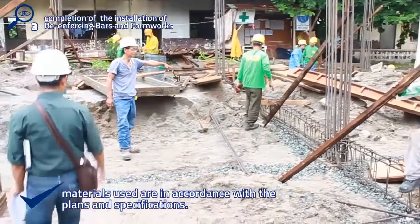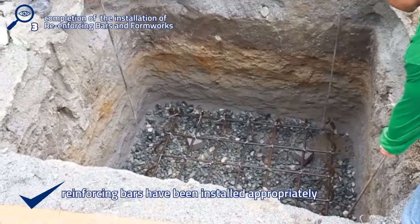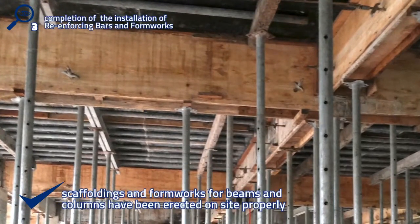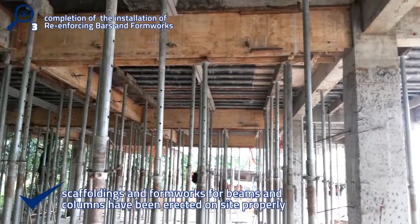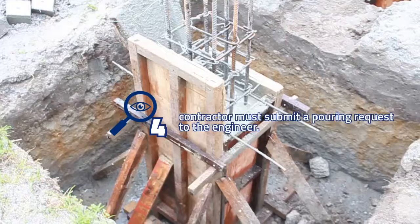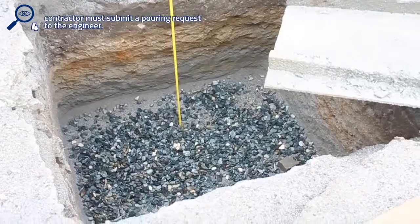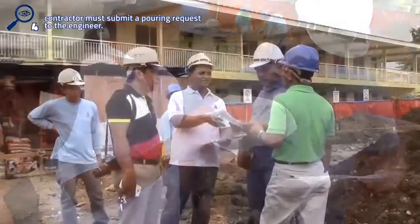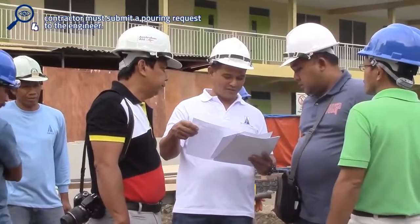That the reinforcing bars have been installed in accordance with the plans and specifications. That the scaffoldings and formworks for beams and columns that have been erected on site comply with the plans and specifications. Key inspection point 4. Once the contractor is ready to begin the structural concrete, but prior to the concrete pouring, the contractor must submit a pouring request to the engineer. On receipt of this request, the engineer should carry out key inspection point 4.